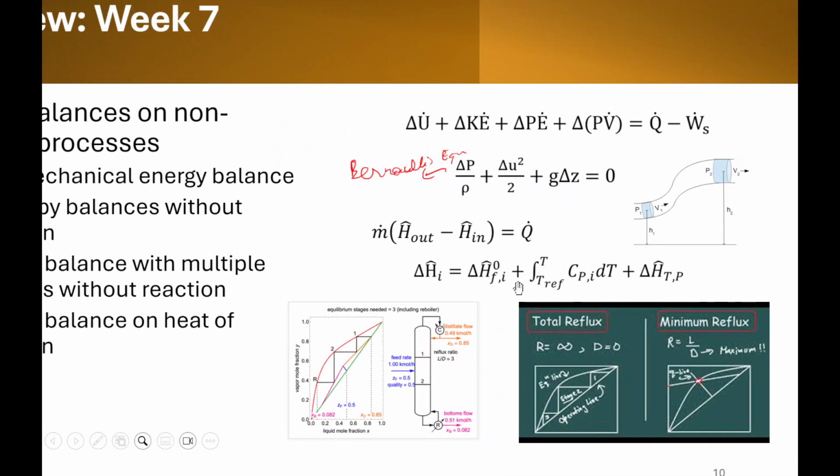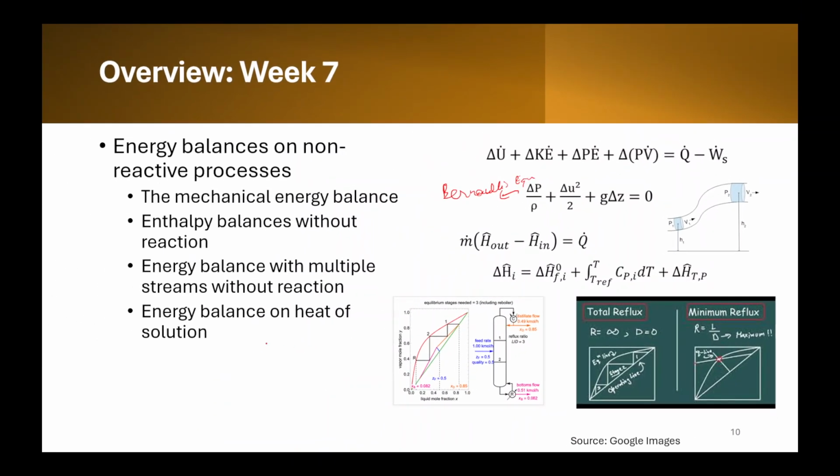If you change the temperature, owing to that there will be some sensible heat, so m Cp delta T, that is your sensible heat enthalpy, and then you add another term. If there is a phase change, you add the latent heat term.